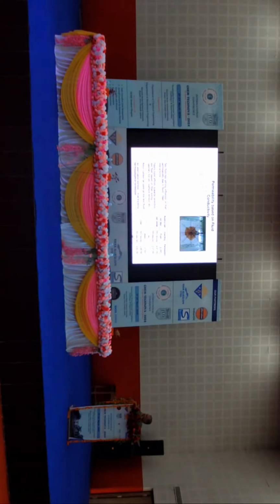We used different injection fluids like honey solution, glycerin solution, water and so on, and we understand that permeability is a physical property of the fiber mat which should not differ with the test fluid used. But from the results we obtained a different permeability for different liquids used. Ideally it should not vary.